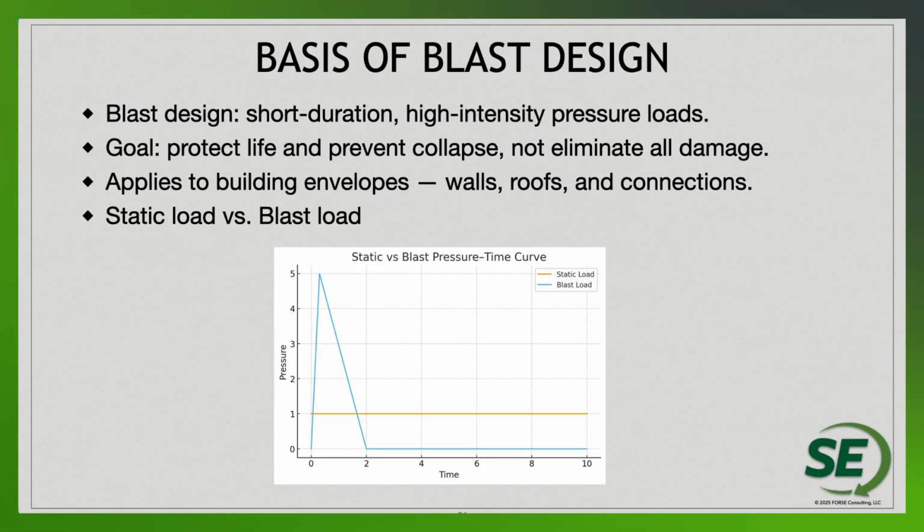And so with that context, let's talk a little bit more about the fundamentals of blast loads. They're very different from wind or seismic. They are short duration, really high intensity pulses. To compare it to a static load, you can see in the graph the difference: static loads are constant while blast loads spike very sharply and then decay within milliseconds. So the duration is so short that inertia really controls the structural response. So definitely not the same as a static type of load.